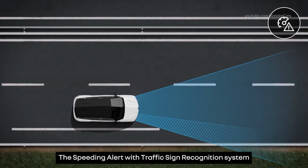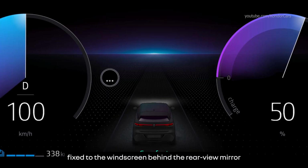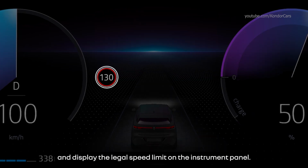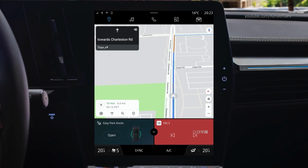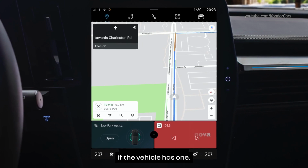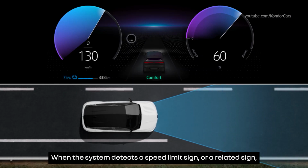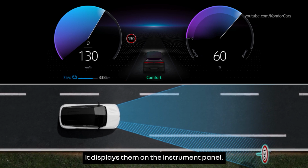The speeding alert with traffic sign recognition system uses data mainly from the camera fixed to the windscreen behind the rearview mirror to detect speed signs and display the legal speed limit on the instrument panel. The system also uses data from the navigation system if the vehicle has one. When the system detects a speed limit sign or a related sign, it displays them on the instrument panel.